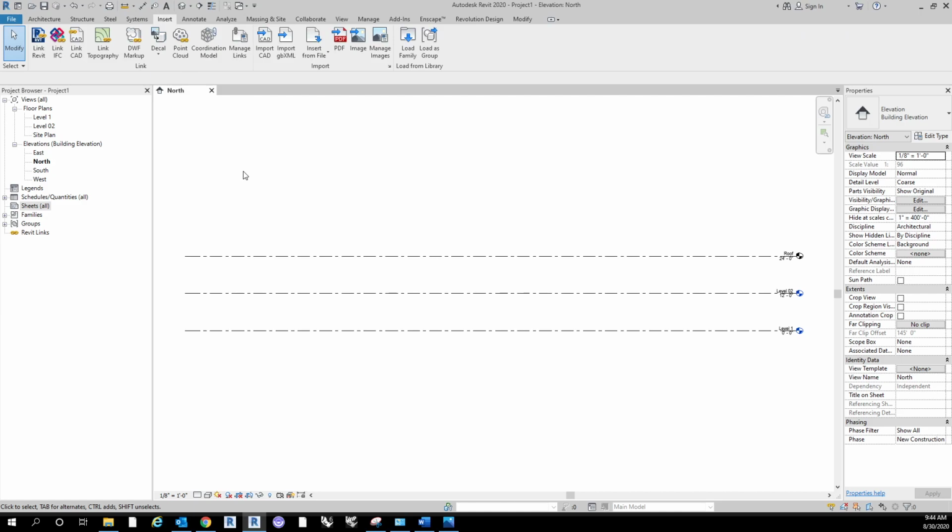Insert. So insert is where you can either insert a Rhino model or an AutoCAD file. You can link other Revit models into your project. So say we have, for the high-rise project that Little is working on, an office model, a site model, a parking deck model, a hotel model, and then a context model.